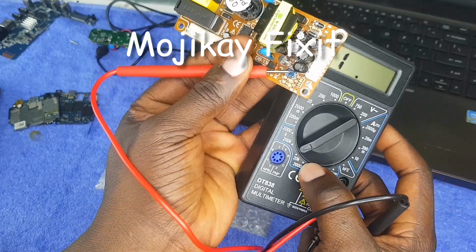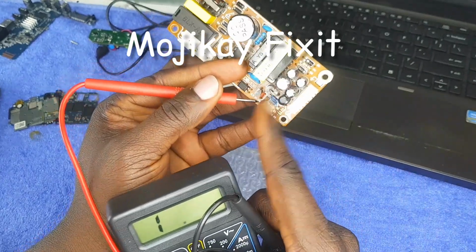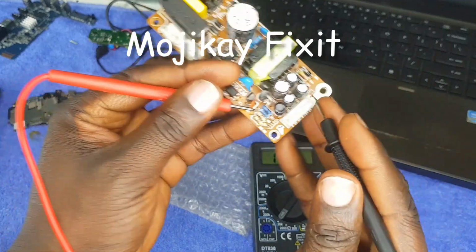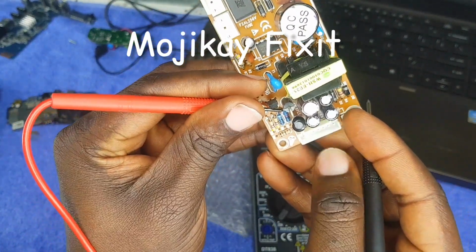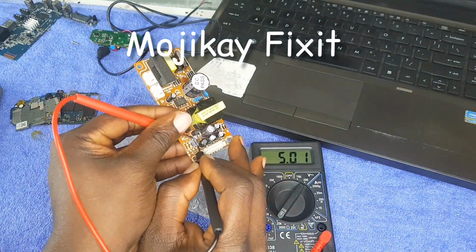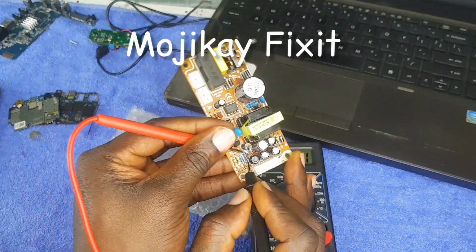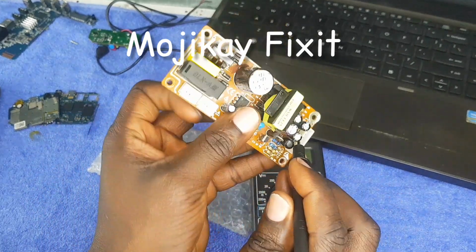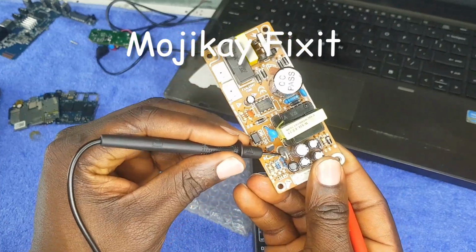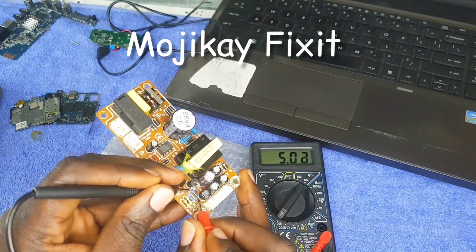You can put it on 2000, it doesn't matter, but the value of this resistor will determine. But I'm very sure the value of this resistor is more than 2000, so I'll put it on 20k so we can get some reading. Okay, so I'll put my red probe here, black probe here. Then you can see the reading is 5.01k resistance reading. That's the resistance reading. Even if you switch your probes, the black probe comes here and the red probe comes here, it's still going to give you the same reading. Do you see that? It still gives the same reading.